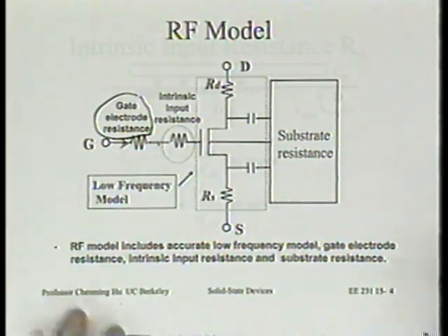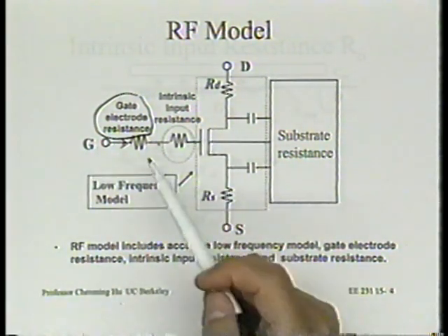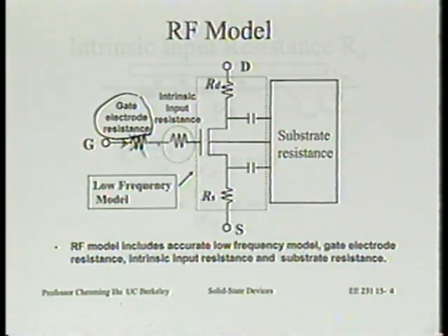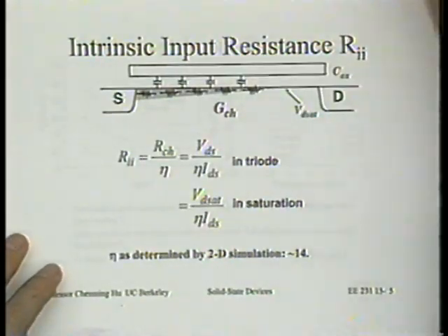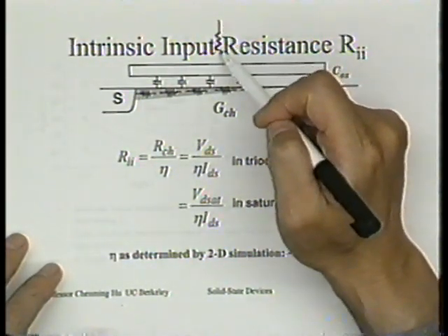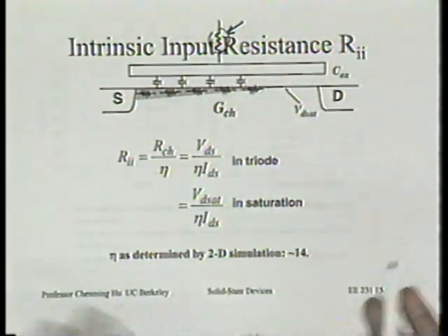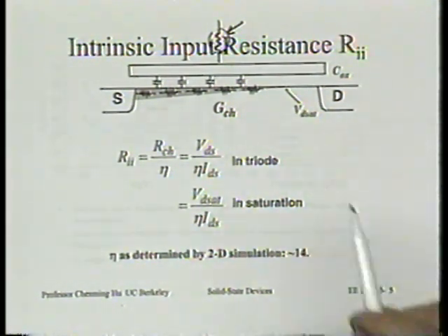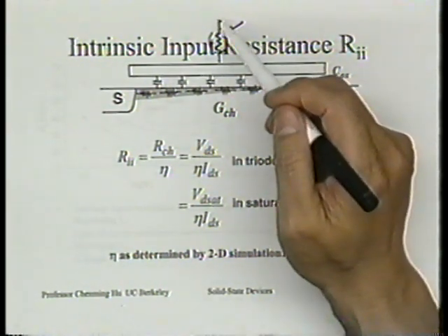Okay? All right. So it turns out the gate resistance, the way perhaps you're thinking about gate resistance, is not important, because it's a small part of what's causing the voltage drop. Why is that? The reason is this. As that gate current flows through the gate resistance, this may be due to the polysilicon resistance. As I said, that's not a dominant component, certainly not an interesting component. There's still going to be a voltage drop as a result of this AC current flow. Where does this AC current flow?